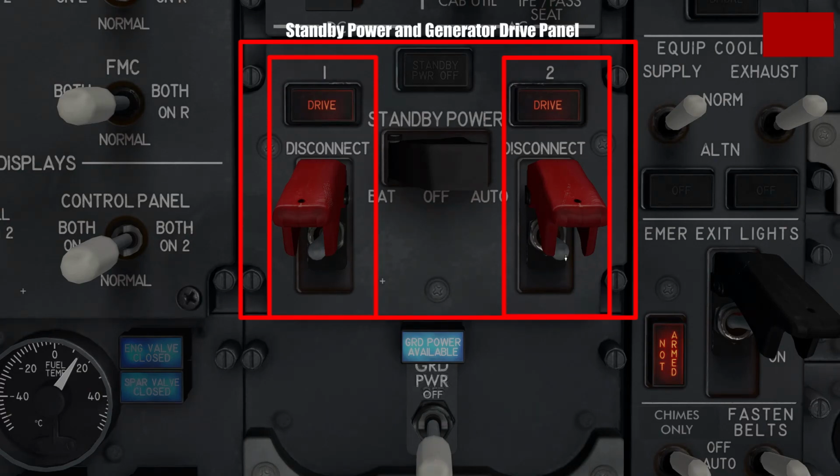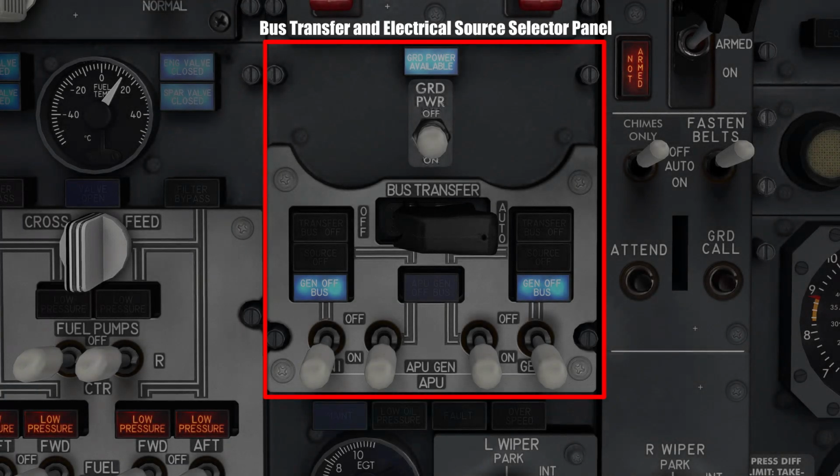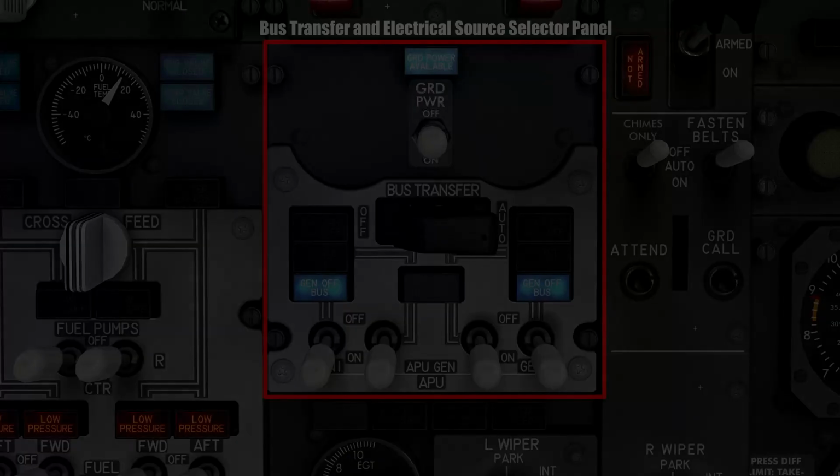Only certified technicians and engineers are allowed to repair the system when the aircraft is safely on the ground, and even then the entire engine needs to be reopened and stripped apart for a new generator to be installed. Again, a system that doesn't need to be messed with for normal operations. Below this is the bus transfer and electrical source selector panel. However, we will come back to this panel after first looking at the APU panel, as it is important to first understand what the APU is and how it works before selecting it as an electrical source.